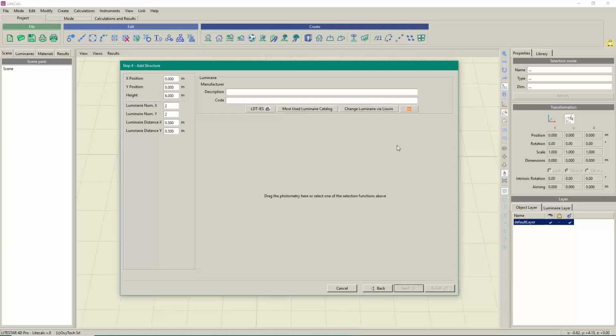because this is another big advantage of using Lightstar 4D: you can import the 3D of the high mast, and so you can exactly place the luminaires. Whenever you select the high mast panel and get the image, you can also transfer the image to the installers, and they will have exactly the different positions of the luminaires in 3D, so that they can immediately recognize where to place the luminaires. So it is really very, very helpful.